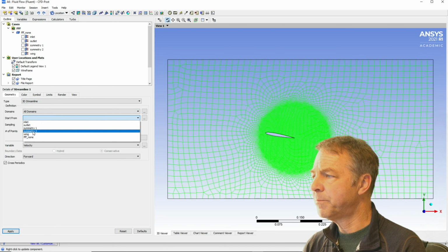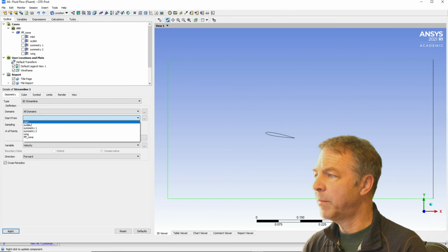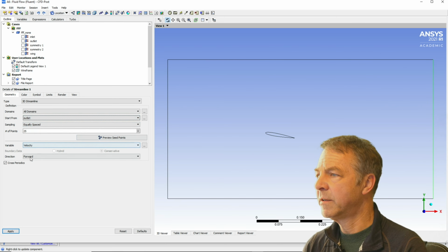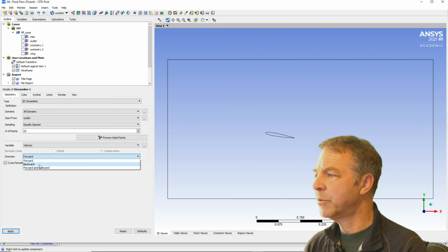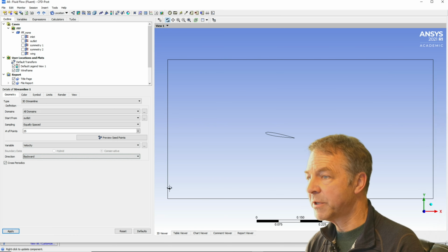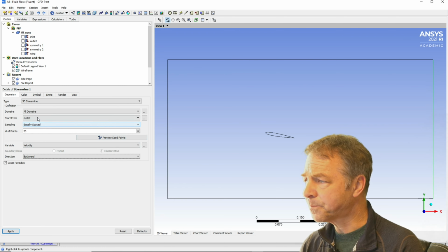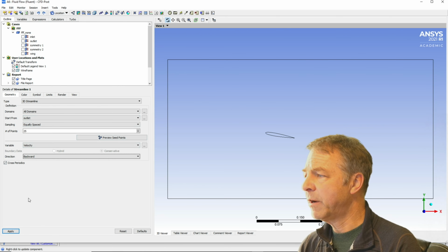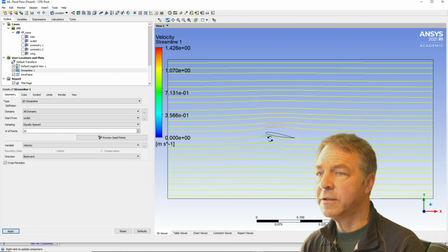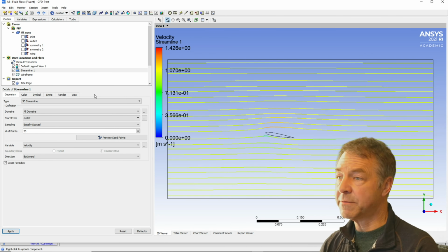We will start from, we could choose where we're going to start from. I'm actually not going to start from the inlet. I'm going to start from the outlet, and I'm going to go backwards. And the reason I'm doing that is because I chose as the inlet the horizontal and the vertical faces, and it will just make a weird result. You can try it. And so if I start from there, I'm going to measure the velocities, and if you do that, you can see that this generates a perfectly realistic looking set of streamlines.